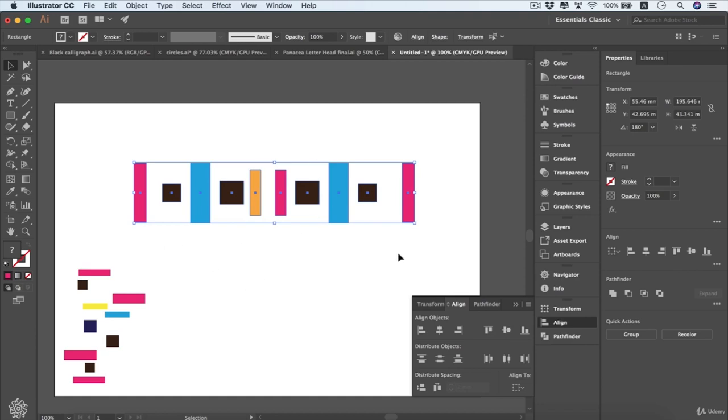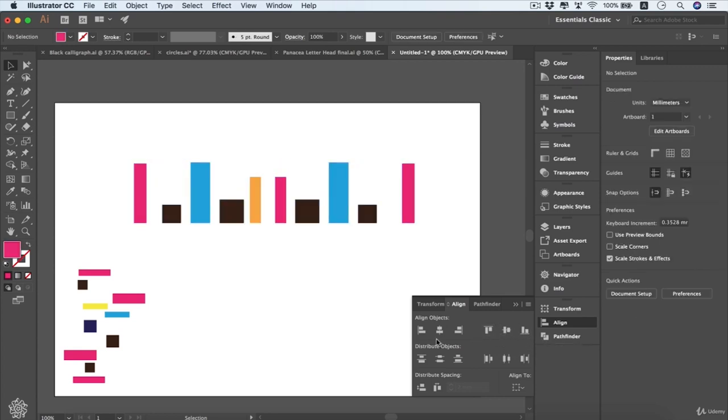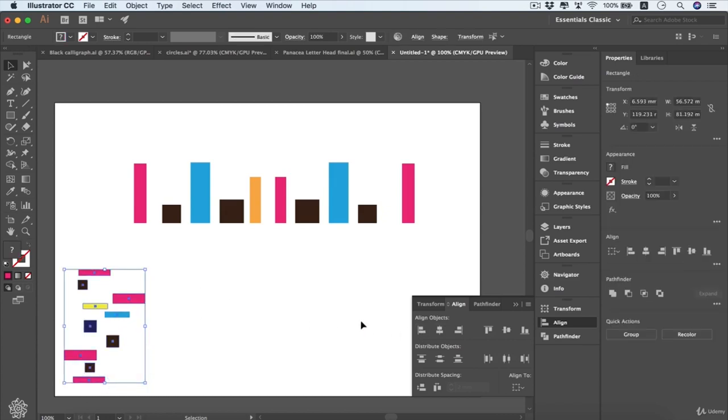as you can see. And if we need to align them to the top, we're going to be selecting that one. And if we need to align to the bottom, from here as well. And we can be testing the horizontal options on these vertical elements. We can be selecting these and aligning to left from here, or right, or center.